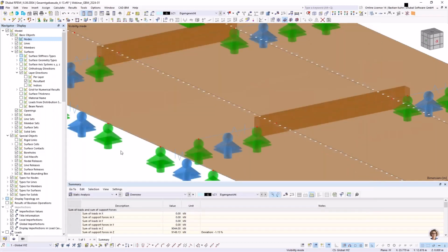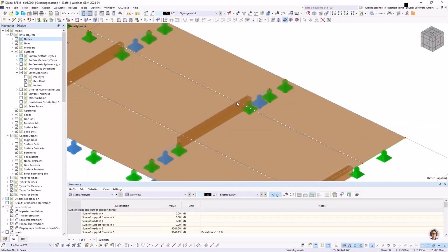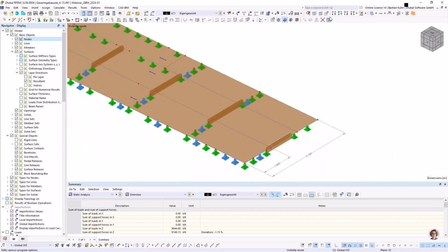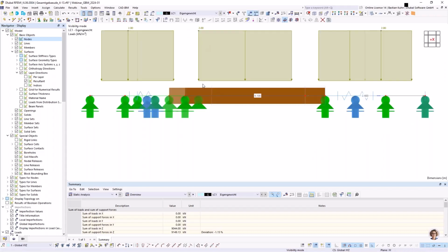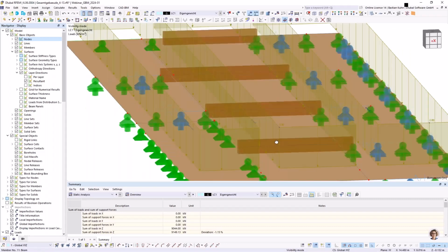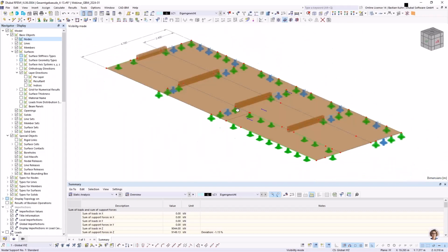calculated, in order that the structure is not collapsing, because obviously when we look in X direction on it, if you put a load in here, I can also show the load in here, and you have no support, no downstand beam, it's clear that this will collapse, because there's no moment rotation, it's not moment stiff in this direction for this load behavior. Okay, so this is the structure itself.